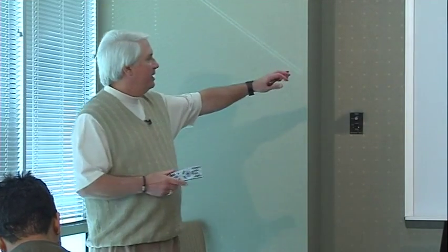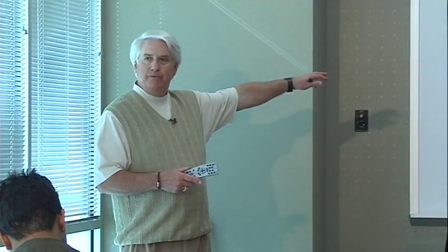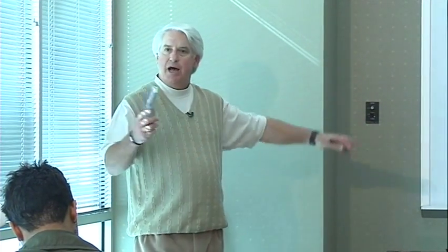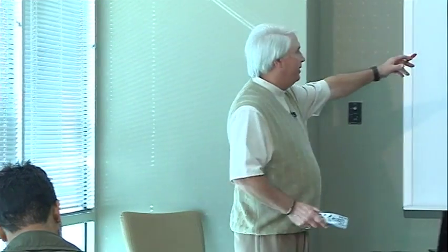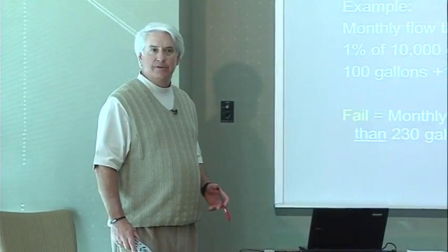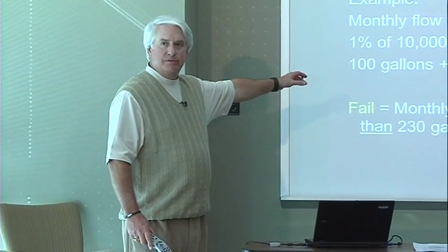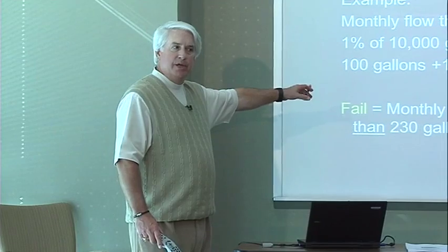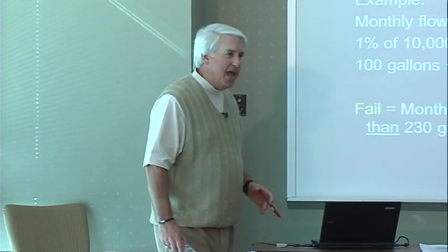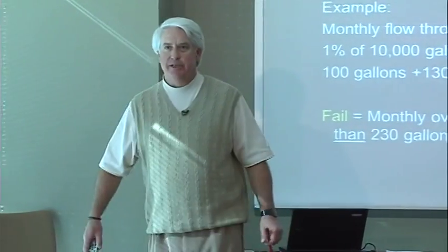Now, let's go back and look, while we're talking about this, look what would happen if we had the 1,000,000 gallons from those high flow throughput facilities. You take 1% of those 1,000,000 gallons a month, you're going to come up with that 10,000 gallons. So here, you could pass this form of monthly release detection as long as you didn't release 10,129 gallons worth of gas a month. You could pass this for monthly release detection. And then, you know, you're probably going to get fired. Where did the 10,000 gallons go? But anyway, that goes to show you.